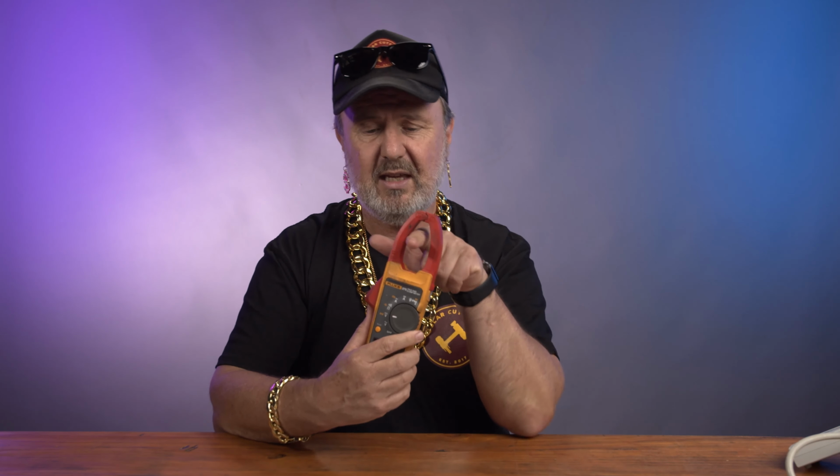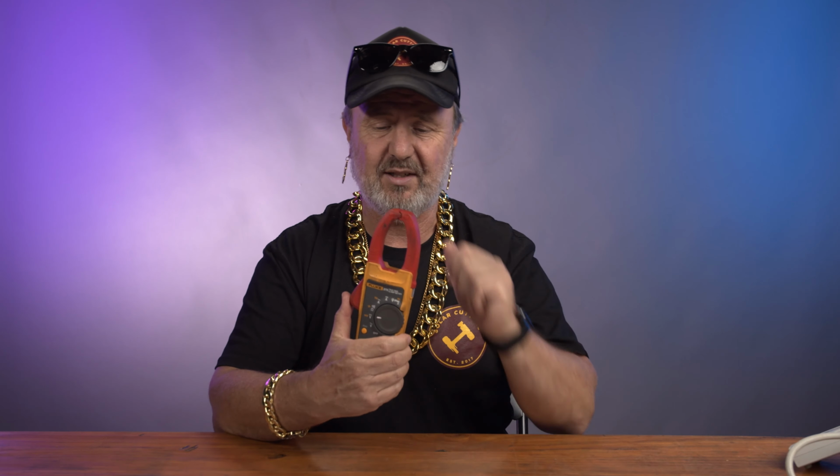Now, this is a clamp meter that can measure the current passing through a conductor. So you actually have to clamp it over a single active conductor. So therefore it is really an electrician's tool because you're going to be in a switchboard. You can't just clamp this around a power cord, which embarrassingly I had tried once and wondered why I always measured 0. It's got to measure one directional flow, so it can only go around one conductor, like the active conductor.